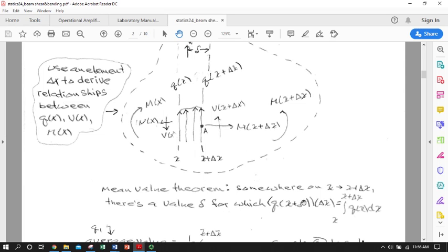If we put the height of that rectangle at just the right location as defined by the y value of your distributed load function, and then multiplied by the width of the rectangle, which is our delta x, we'd get something equal to the full area under the curve, which is effectively our resultant force. Aha! That effectively says this delta, which is somewhere between x and delta x, that's the position of our equivalent resultant force produced by that distributed load.